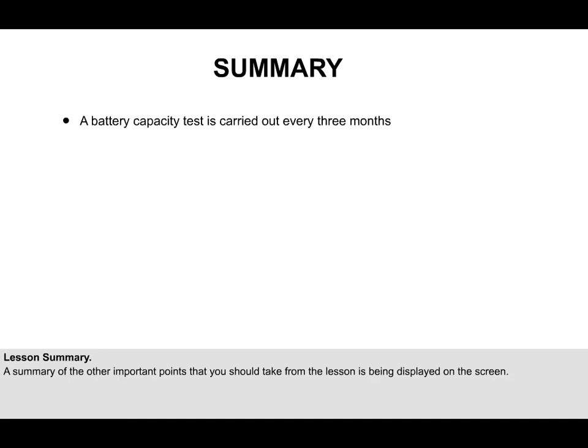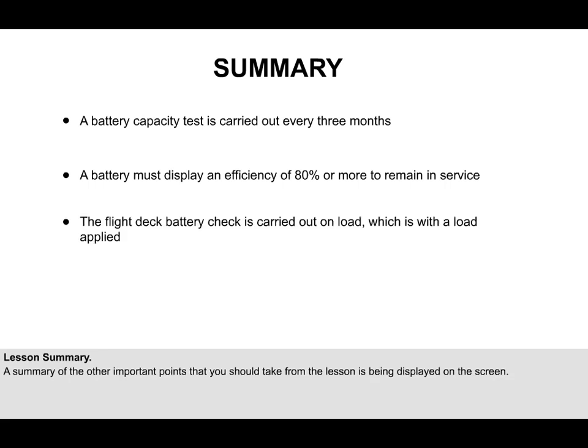A battery capacity test is carried out every 3 months. A battery must display an efficiency of 80% or more to remain in service. The flight deck battery check is carried out on load, which is with the load applied. If one cell fails, the battery is unserviceable and must be replaced.